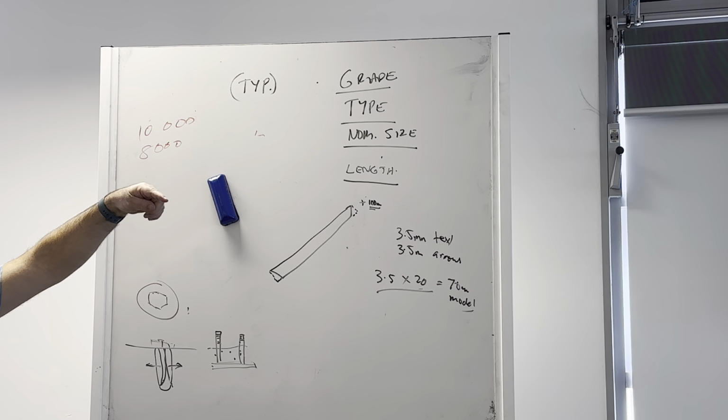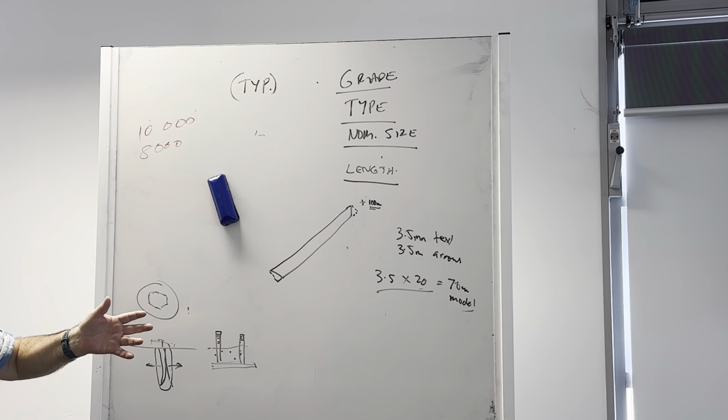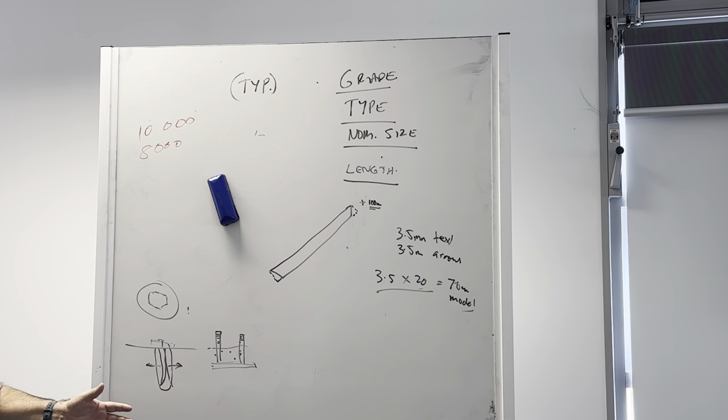you could add all them up. In which case, I was going to say just add 100 mil to the total, but the problem with that is that when you add them all up, you might just go over what the timber suppliers have got. So if you are going to add them up, probably best to add 100 each time. All right.